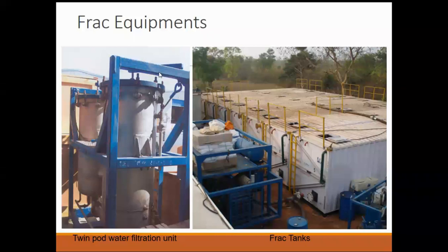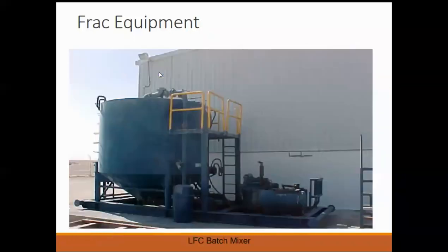There are membranes which filter the water to remove all the debris, and the size of that membrane is in microns, around 8 or 10 microns. And you can also design it on the basis of your requirement.